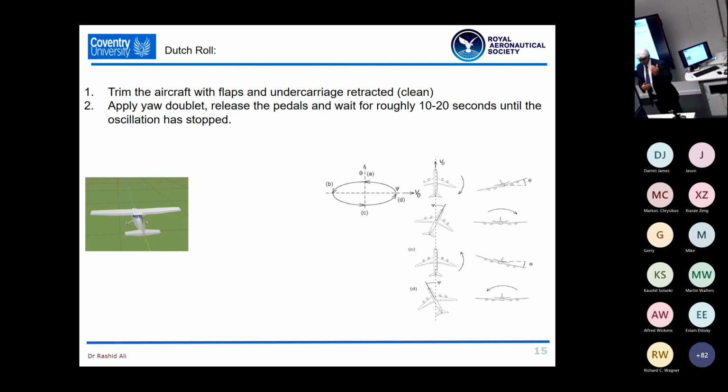By plotting the yaw angle versus the roll angle, we can see whether the aircraft is heavy in yaw, which is the wing translating backwards and forward, whether it is predominant in roll, with the wing going up and down, or whether it has an equal amount of yawing and rolling motion, where the wing will be seen to be executing a circular motion during the Dutch roll.